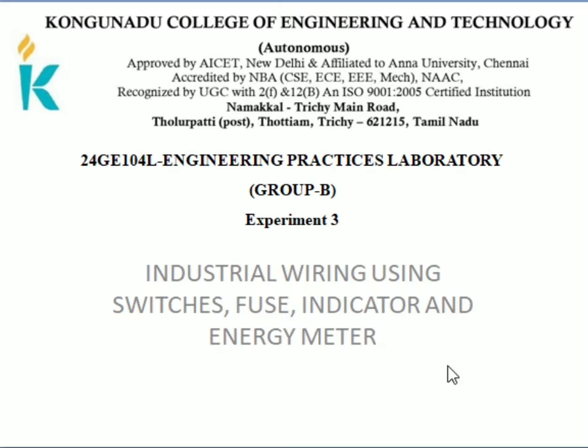That's why we use a 3 phase power line supply for the high power machines. High power machines also consume a high amount of current, which a single phase supply can't provide. So that's why we use a 3 phase line on the industrial side.